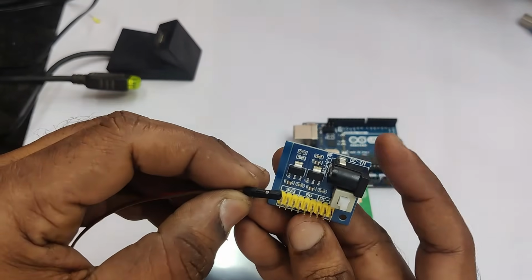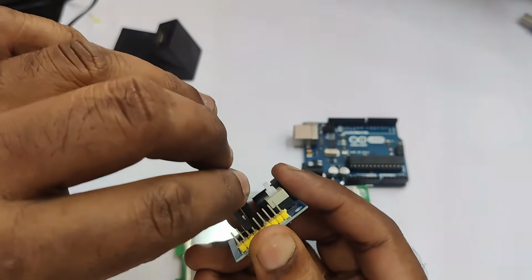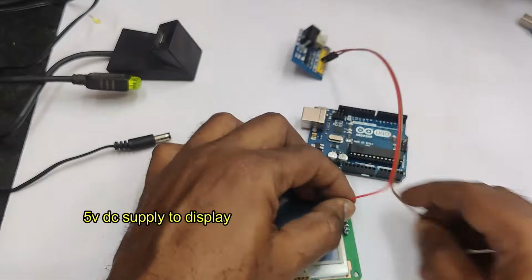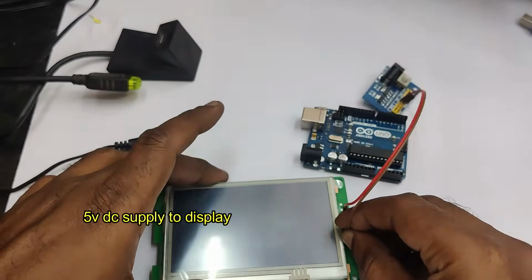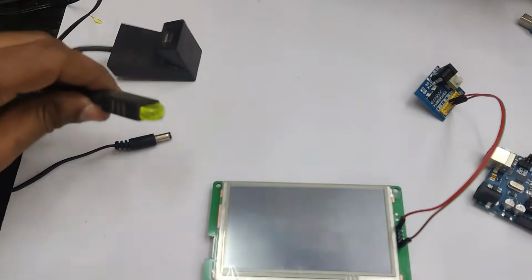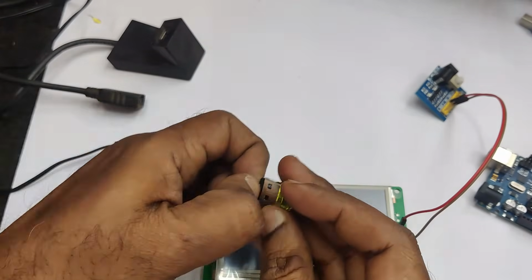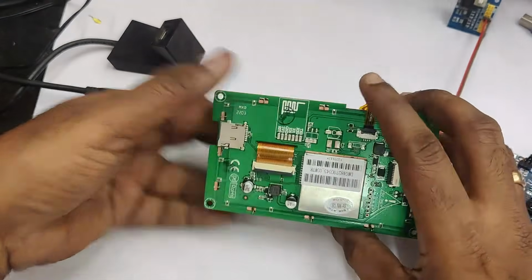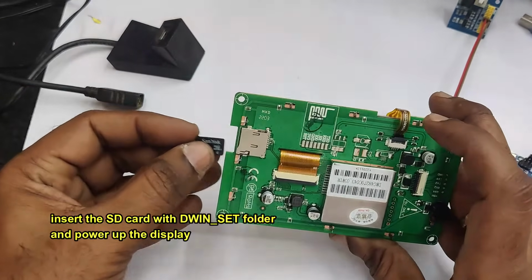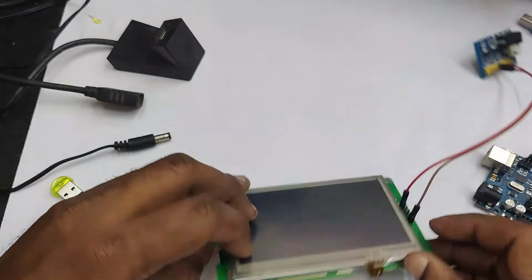Now let us connect the power supply to the DWIN: supply to supply, ground to ground and 5 volt to 5 volt. Remove the SD card from the card reader and plug into the DWIN SD card holder. With power on, do not do this. Only in the power off condition you have to plug in the SD card. Now after inserting the SD card, switch on the power to the display.